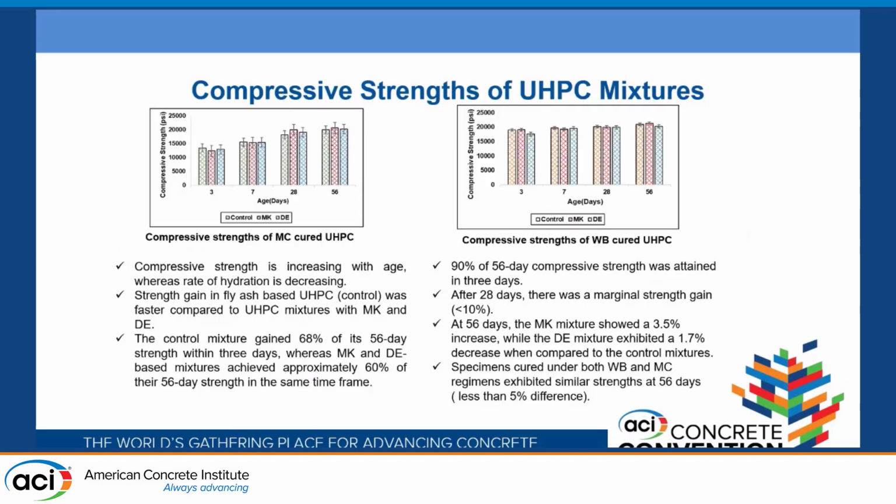Here we can see the effect of SCMs on the compressive strength in both the curing regimens, MC and WB, at various ages. In moist curing condition, the compressive strength was increasing with age, whereas the rate of hydration was decreasing.